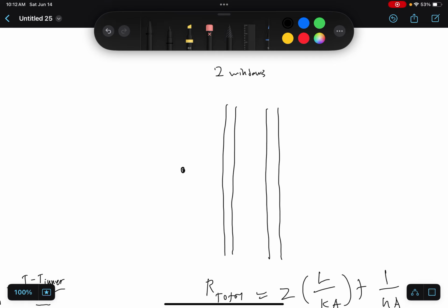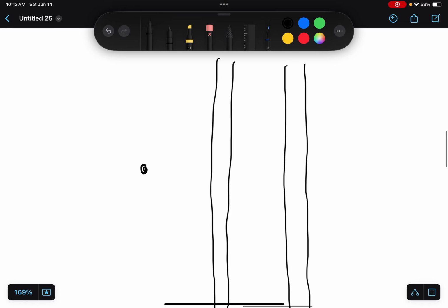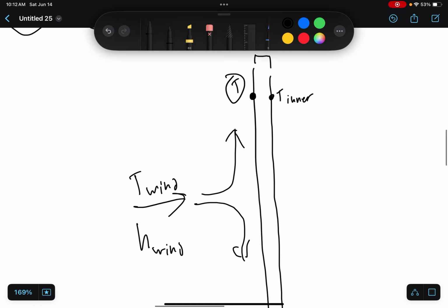And just like in circuits, or what's the other class, Physics 2, where they go into electricity and resistance and voltage and current, you can literally use those exact same principles here. So we've got a couple different thermal resistances. We've got a thermal resistance of convection between the air, T, is that what I called it over here? T wind.